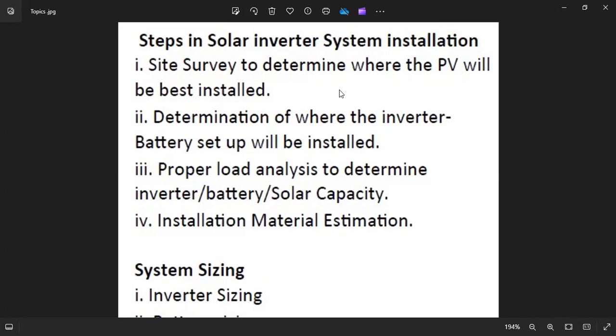They come with inbuilt battery monitoring systems attached to them that monitor the temperature, and monitor the voltages of each cell, you understand. A complete lithium-ion battery comprises so many cells. If you happen to open it, you discover that it has so many cells, some come in 3.2 volts, some in 3.7 volts. They are assembled to form a complete system that gives you the desired voltage you want. So you discover that it comes with a battery monitoring system, which we call the BMS.